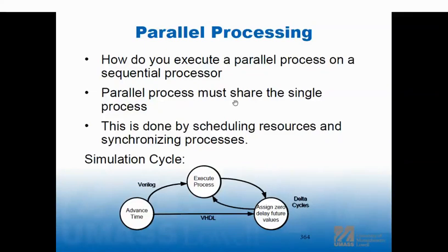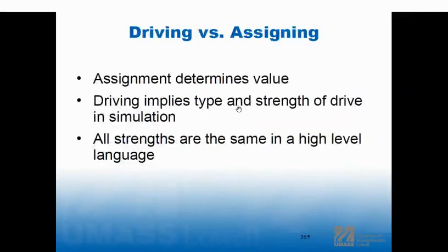The slides, I think, are the last slides tonight. Driving versus assigning. This brings up another point. Less of an FPGA point, more of an ASIC point. ASICs are generally designed where you take your logic design and you put it into a top level. So the complete logic design is at that top level. And then there's another big module, and it's the I/O. And every I/O on the top level connects to one side of the I/O block. The other side of the I/O block connects to the edge of the chip.